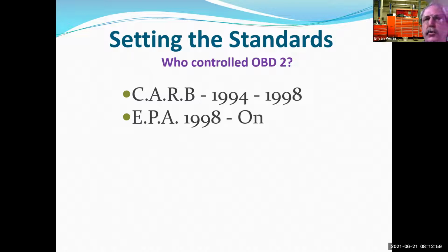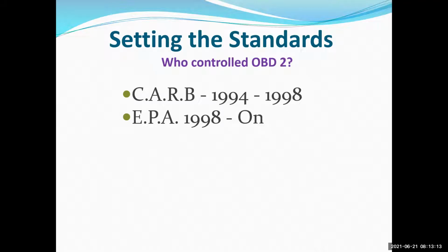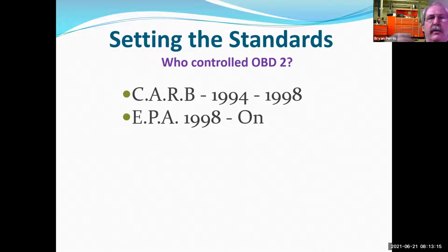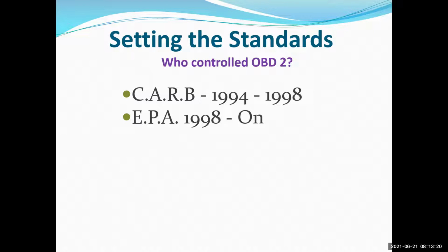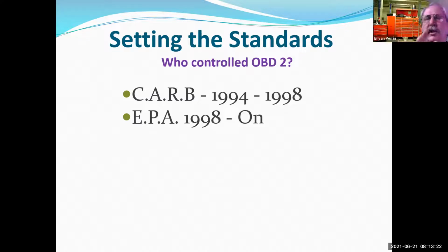We have some new things that are available on newer vehicles than we had on older ones within that structure. So if I'm using a really old tool, it might not access certain modes of operation. Okay. But I'm able to use the same tool. The difference that we had for a while was pre-CAN vehicles versus post-CAN vehicles, and a lot of early scan tools couldn't talk to a CAN vehicle. Today, all generic scan tools are able to talk to CAN and pre-CAN vehicles, so it's a non-issue.